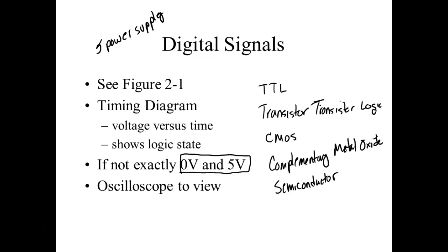The first one is what the digital signal comes into, and the second one is what we take the digital signal from. So TTL has the input on a transistor, and the output on a transistor. That's why it's called TTL. We got RTL, resistor transistor logic, with input on resistors and output on transistors. We got DTL, which is diode transistor logic.